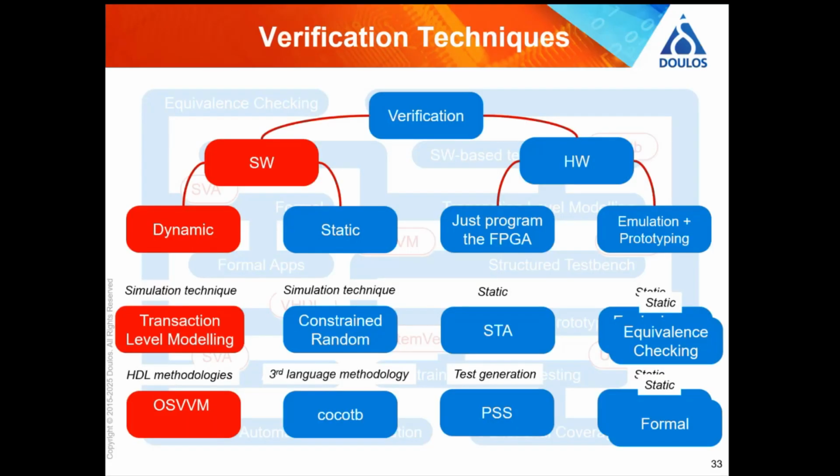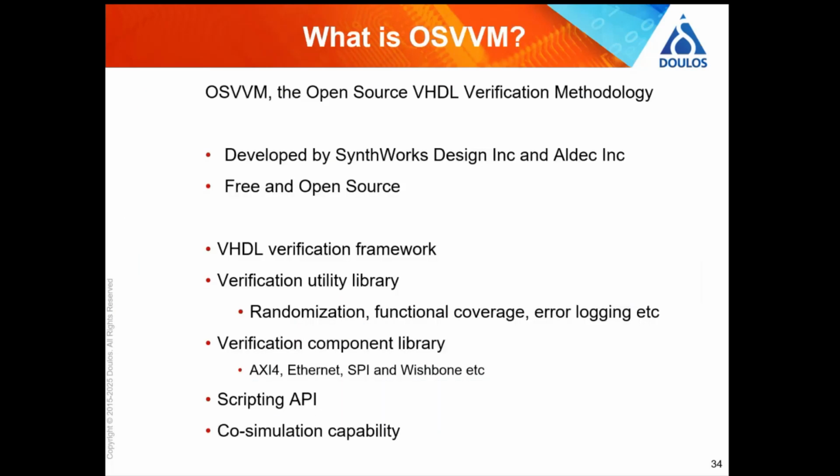So I'm now going to talk about three different methodologies. Two of them are in VHDL, one of them is in SystemVerilog. The first one I'm going to talk about is called OSVVM. OSVVM is an open source methodology. It's developed by a company called SynthWorks in the US and Aldec, one of the EDA companies. As I've just said, it's open source, and it consists of various things.